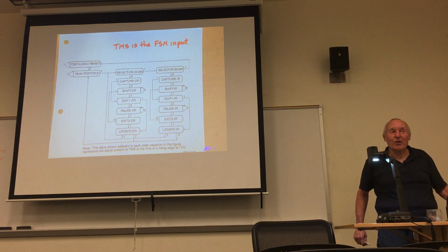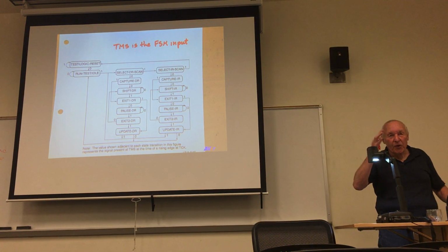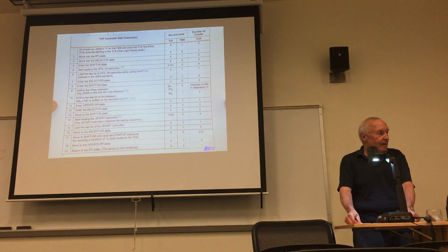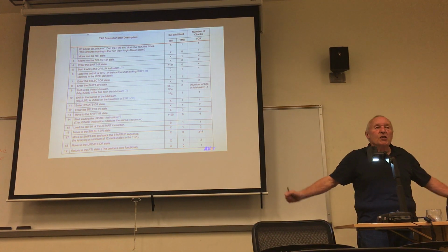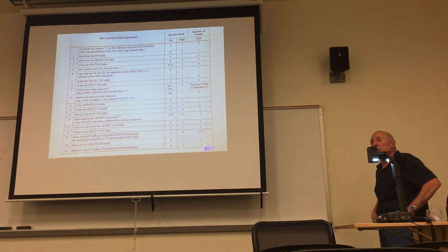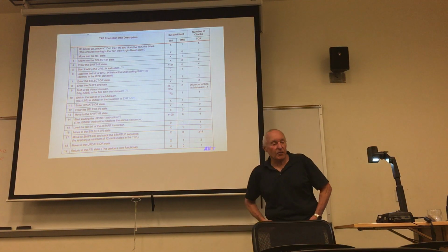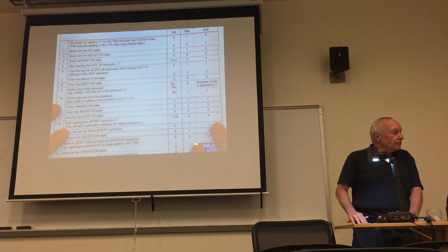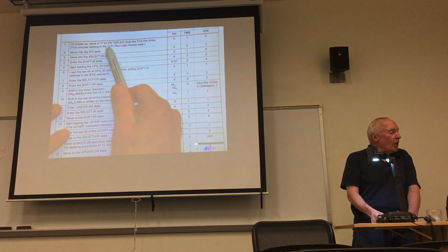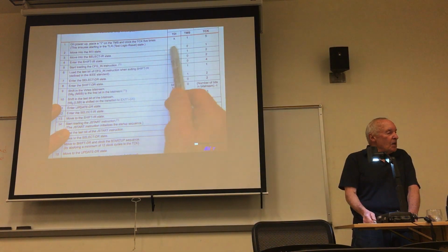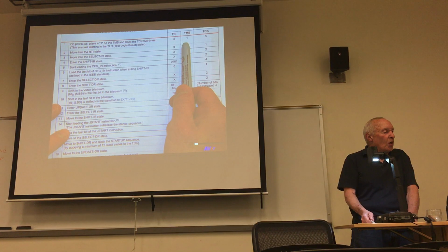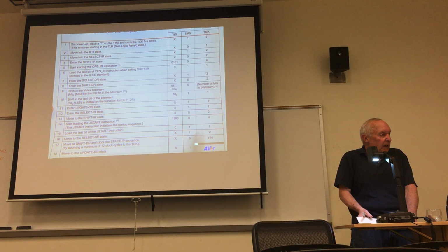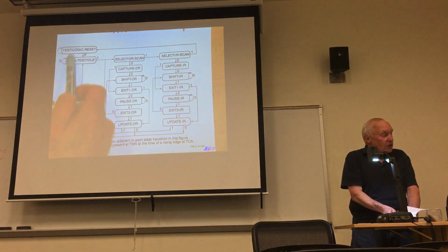Now, I want to show you this, and we'll walk through a few of the states. Those 19 steps are required to program an FPGA using a JTAG interface. So let's take a look at these. On power up, place a 1 on the test mode select and clock 5 times. So TDI is don't care, test mode select is 1, clock 5 times. We just showed that. So that's going to put me in that state.